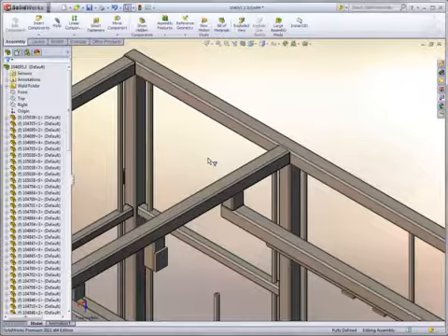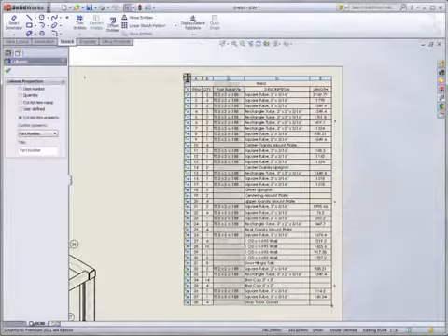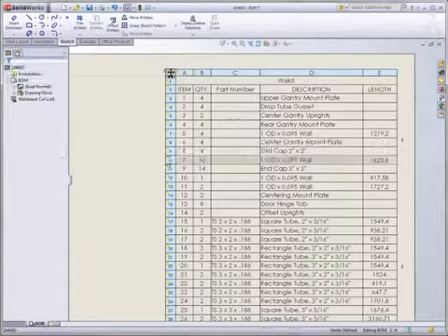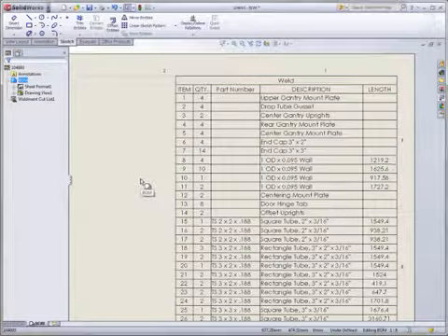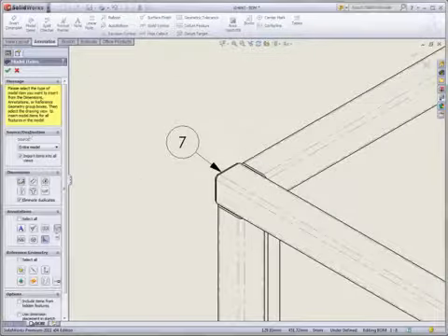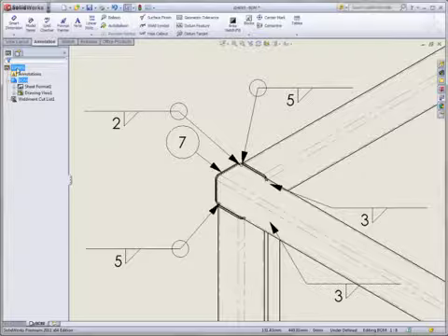SolidWorks 2011 also includes new enhancements for documenting your weldments. Sometimes a simple sort of a weldment cut list isn't good enough. Now you can reorganize cut lists in the same way you do bills of material, giving you full control over the order of items. And like everything in SolidWorks, all of this is associative, meaning annotations for all of the weld beads created in parts or assemblies can carry over to the drawing. This means there's no need to create extra weld notes or caterpillars for documentation. They're easily included, like every other type of annotation.